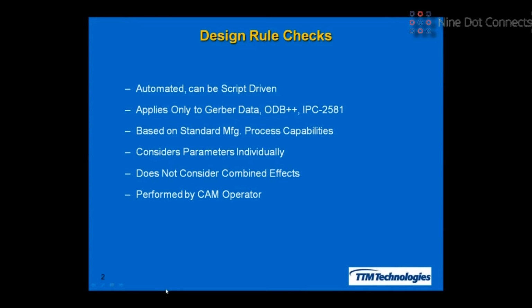And then some basic stuff, rudimentary, like part number or revision level that doesn't match the PO, or the prints, or the data. We've got to make sure that all the revisions and versions match what the PO says. And then I think the next one would be fab print versus the Gerber data. A lot of times fab prints will have adjustments, and maybe the Gerber data didn't incorporate that, or vice versa. It's always good to have the two match, and if they don't, someone's going to stop the job and ask to have that clarified.